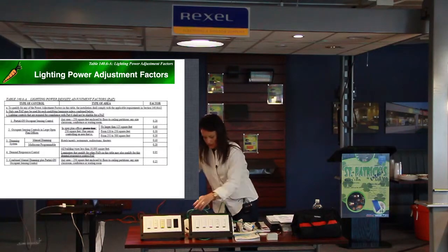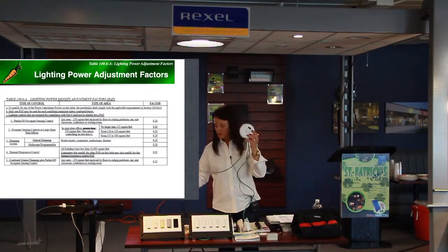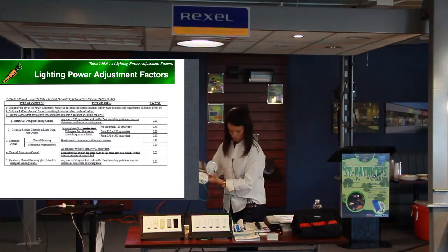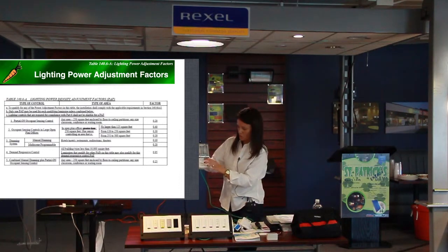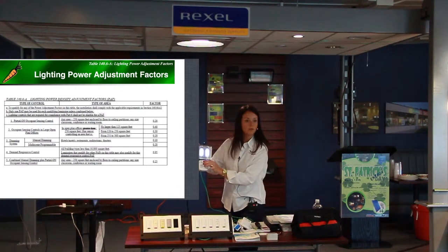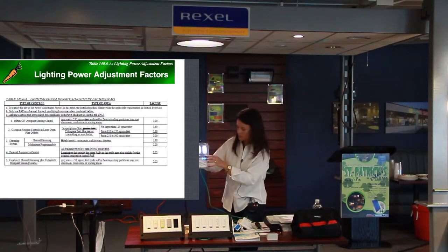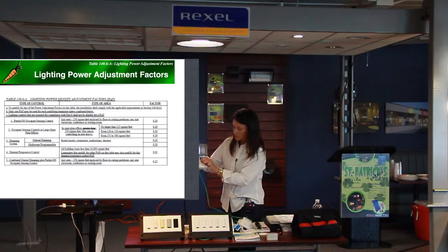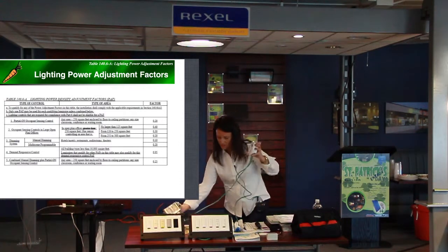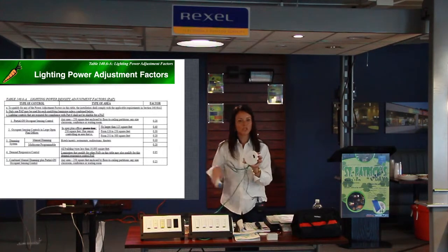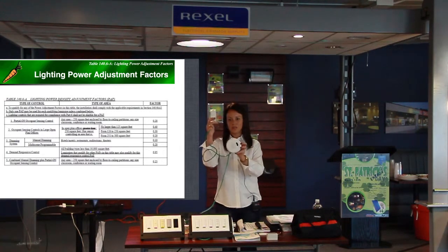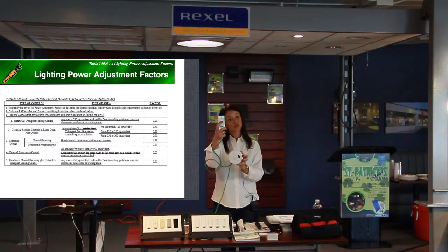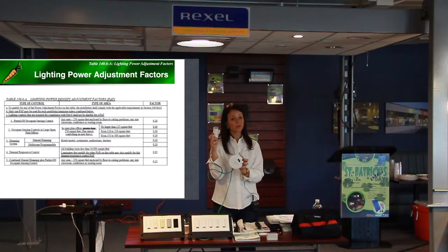The way that it works is if there is a sensor, two relays, one doing, imagine this is fixture number 1 for A and B. So that's just a little demo simulating fixtures. An occupancy sensor and a 2-button switch. So that's called digital lighting management. Half of the lights automatically turn on and the other half will be manual. That's how it comes out of the box.